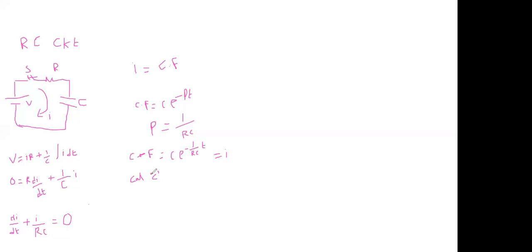At t equal to 0, initially the switch is open. Resistance is a dissipative element, and capacitance is a charging element. Since a capacitor does not allow sudden changes in voltage, at t equal to 0 it acts as a short circuit when the switch is closed.